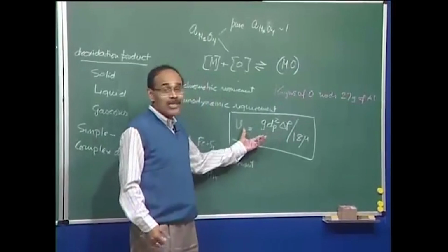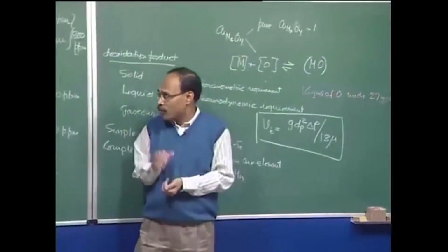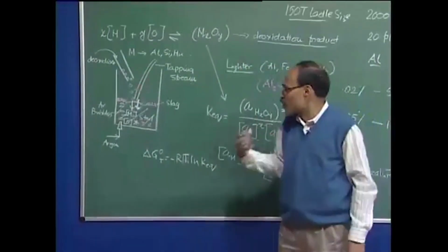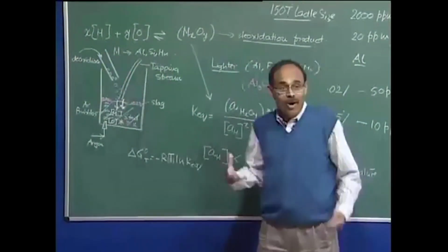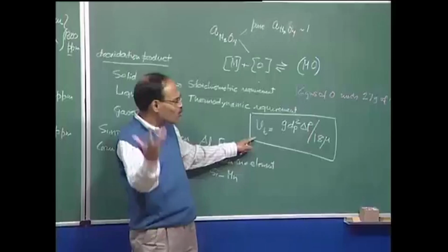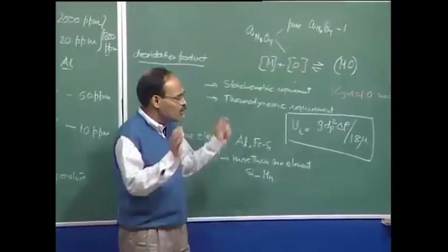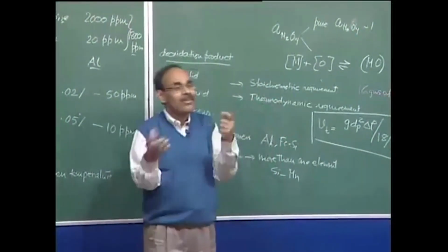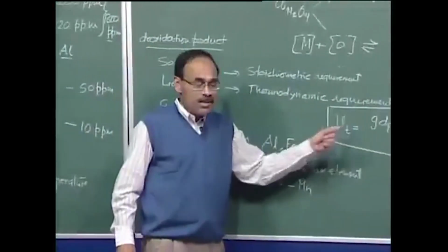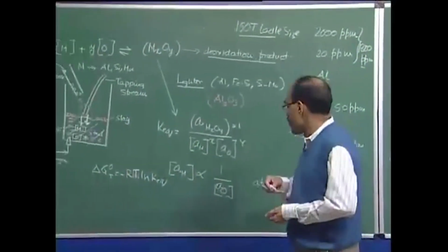Of course, Stokes law is a very simple law. We all know that it is valid for laminar flow, even Reynolds number of the order of 1, which is typically a very weak flow. In this particular system, there is fluid motion also; it is not a particle rising through a stagnant bath. Also, the surface tension in high temperature systems is different, and the particles may completely wet or may not wet. So this is an approximate order of magnitude calculation and need not be taken too seriously. We just get some idea of what size of inclusion can float and what size cannot float, and nothing beyond that. No serious process design calculations or inferences should be drawn on the basis of Stokes law as far as inclusion flotation is concerned.